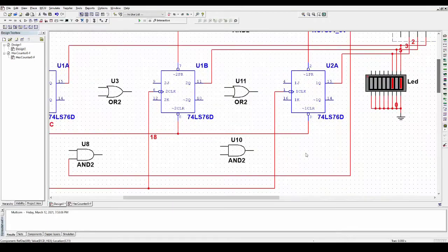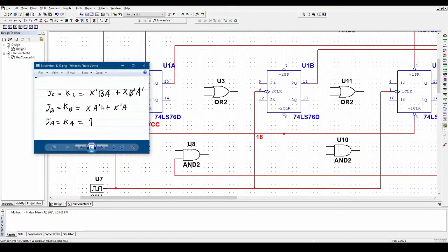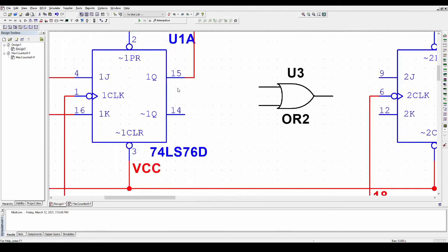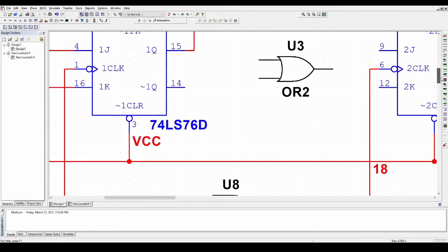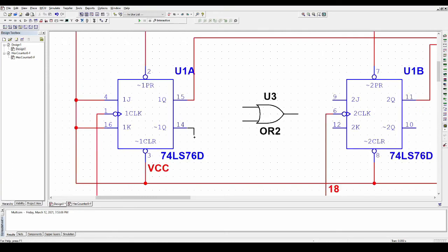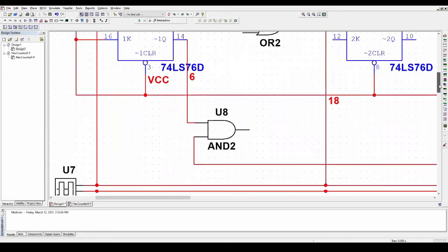Okay, so now I have x coming into this logic gate here, and it also needs a not. So let's look at this flip-flop here. On the top we have the A coming out, and on the bottom we have the A not coming out. So rather than putting an inverter from this wire down to the bottom, we just grab it from here, and we take it there.